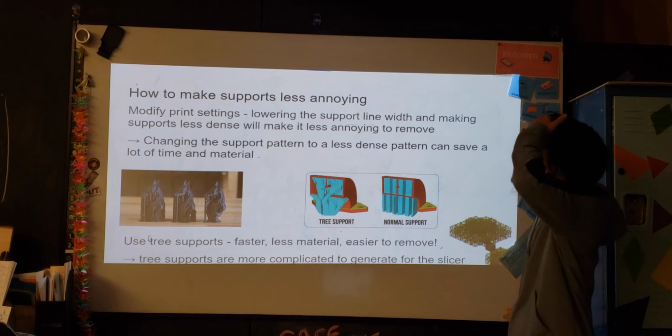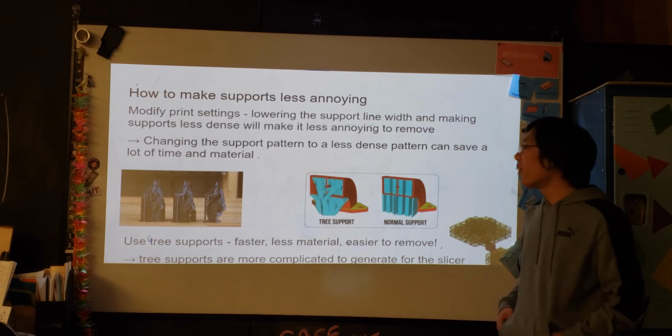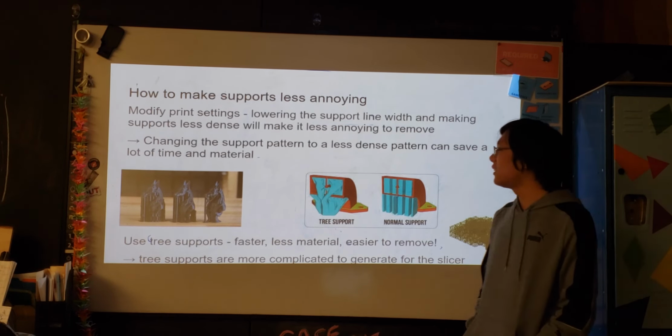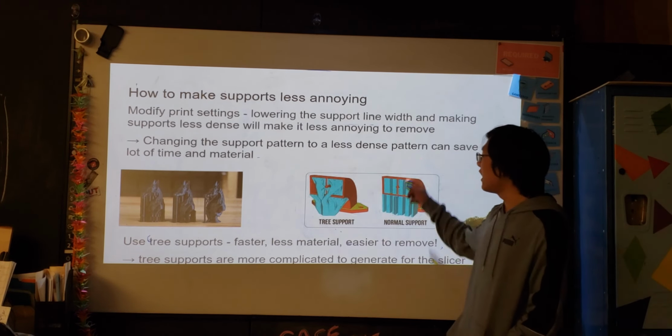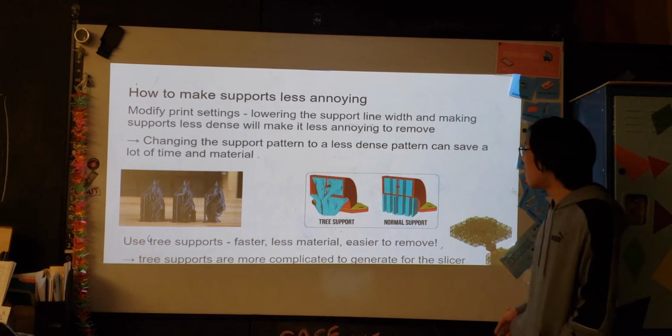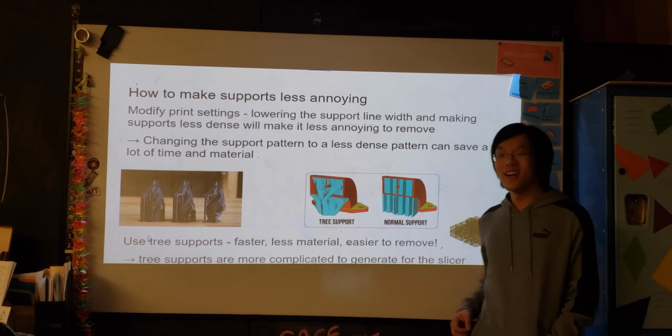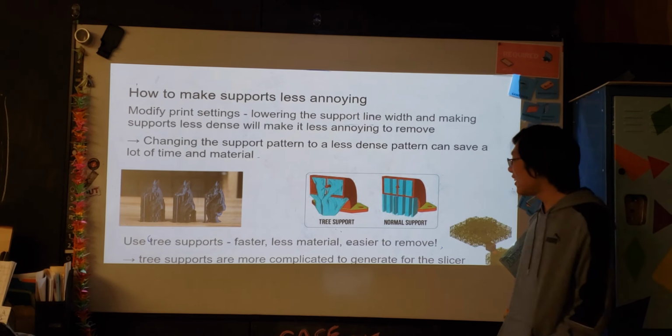So if you need supports, how do you make them less annoying? You can make your supports less dense. You can make them thinner. And you can also change it to a different pattern. Or you can use these fancy new tree supports, the secret sauce of supports.